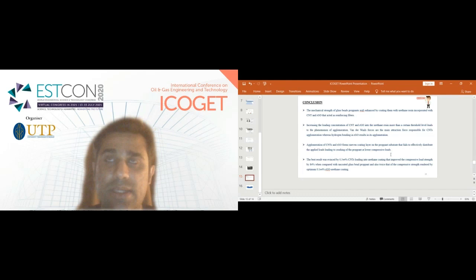So in the case of CNT plus polyurethane coating, the CNT provides a web-like structure around the propellant grain that effectively encapsulates and prevents the fines from releasing from the propellant body, whereas this phenomenon was not witnessed in the case of graphene oxide polyurethane coating.